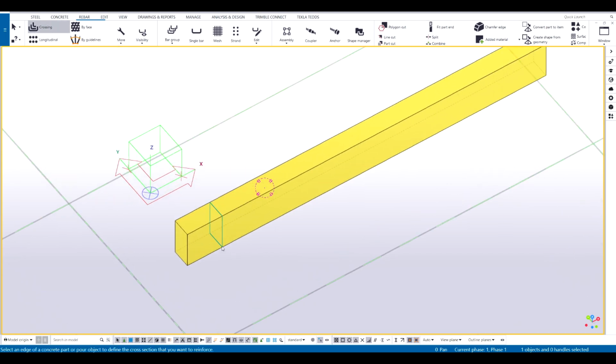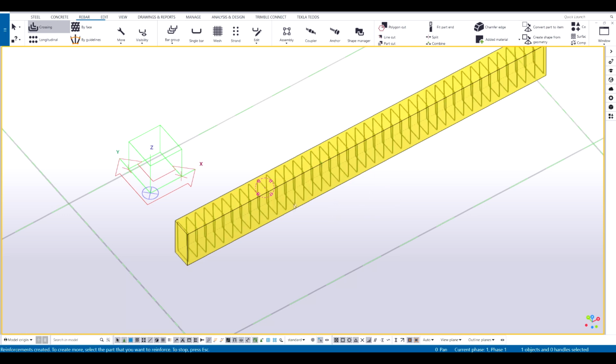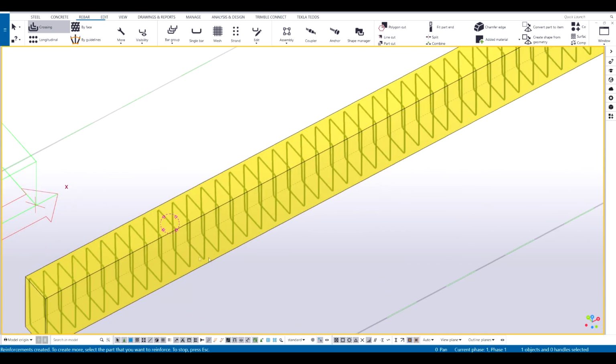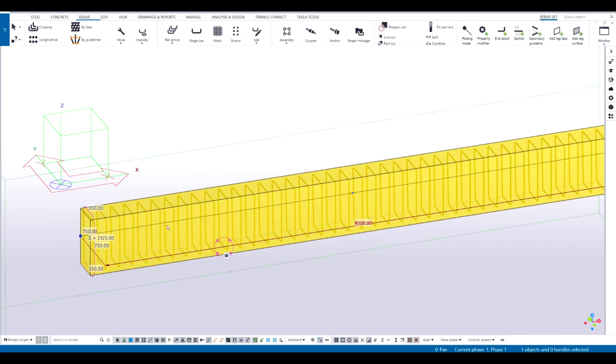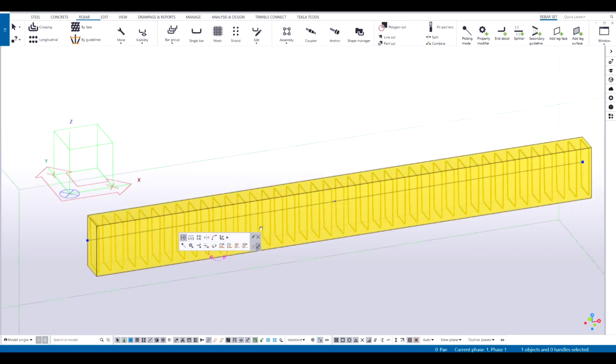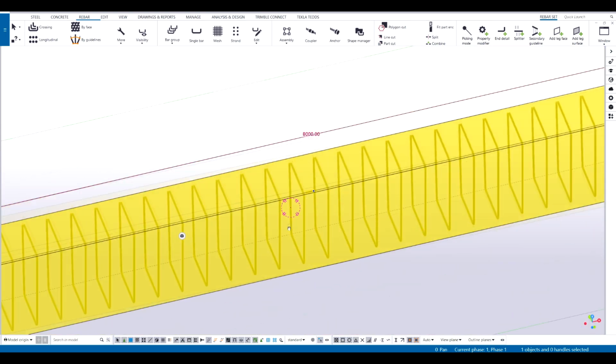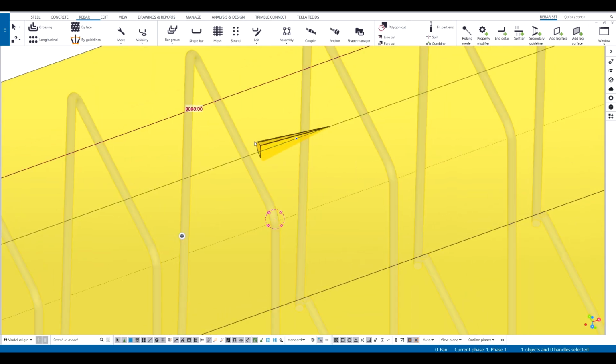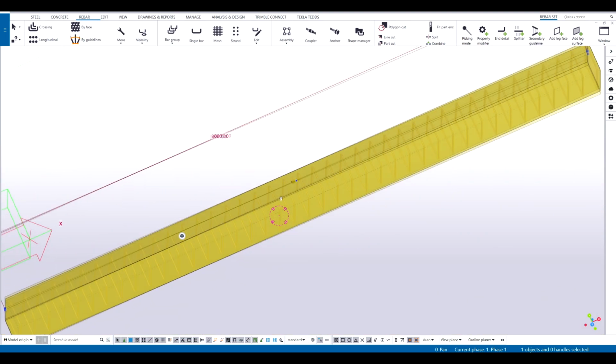And you see, the moment I pull my thing here, it just tries to capture it, and then I can either use one of these or just press the middle mouse button and it puts all of them in. Now if I select them, you can only see this line here, which is a guideline. You see this little cone over here. This left side is the start point and the apex is the end point. Yeah, probably end point, yeah.